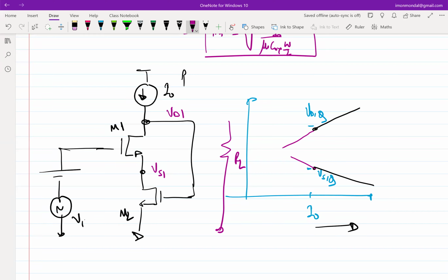which is connected. I want to connect this RL to VD1, because a common source amplifier eventually looks like this, right? You apply something at the gate, you take the output from the drain. So if I simply connect RL to VD1, will it work? No, right? So what is the solution? Put a capacitor, right? So you put a capacitor here, say C2. But if I simply connect it like this, is it going to work?